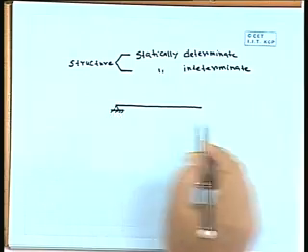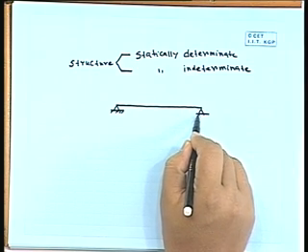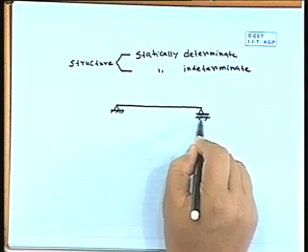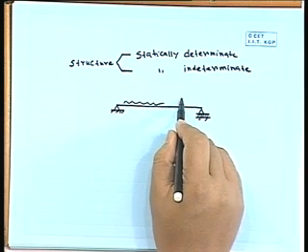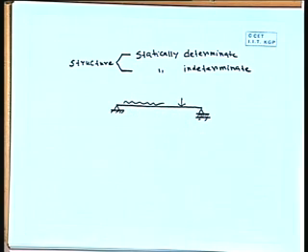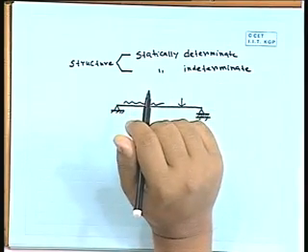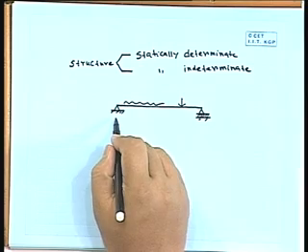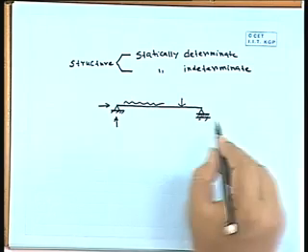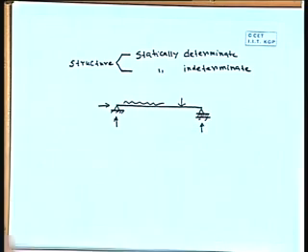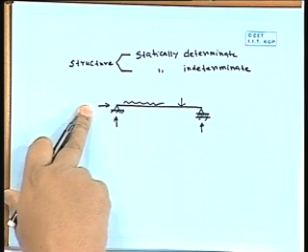Right. Say if we take a beam problem like that, here there is a hinge support, here there is a roller support, and there might be any load on that. Now at the hinge, there will be 2 reaction components, one vertical and another horizontal. In the roller there will be only one vertical reaction component. Here we can say the horizontal component will be 0.